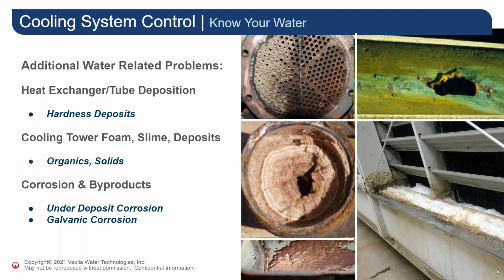Cooling towers can also be impacted by the presence of organics and higher solids loading and begin to foam considerably. Obviously, the picture in the lower right-hand corner shows that. And that can be somewhat of a potential safety issue for your employees, as well as a supply issue with pumps that might begin to cavitate with foaming present.